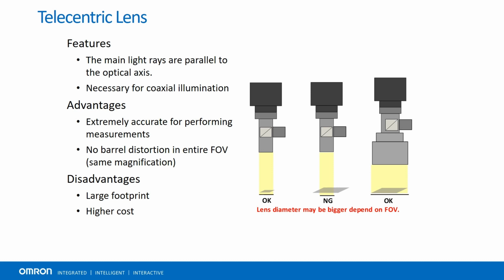Telecentric lenses are the cutting edge of lenses designed for micron-level accuracy measurements. Used in Omron's automated optical inspection line, when combined with high-resolution cameras, we are able to measure distance and color up to a 5-micron accuracy. This allows us to make judgments around the quality of a solder joint and flag for solder defects the human eye could never pick up upon.